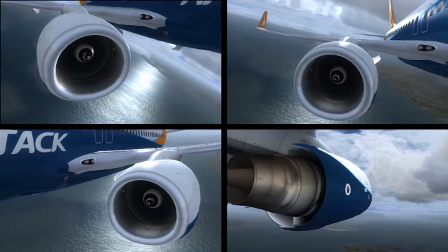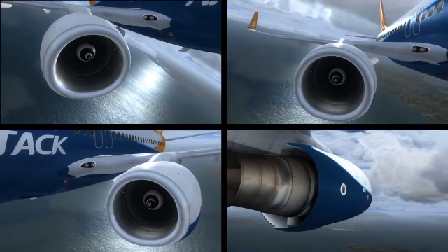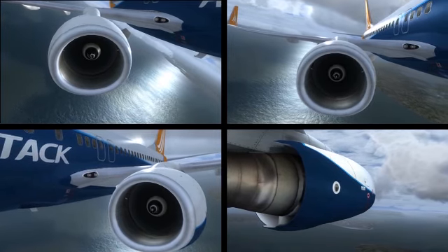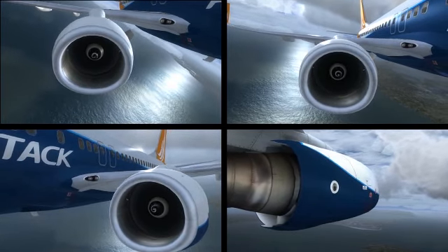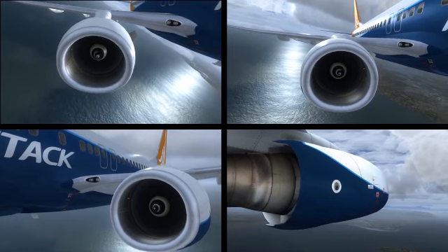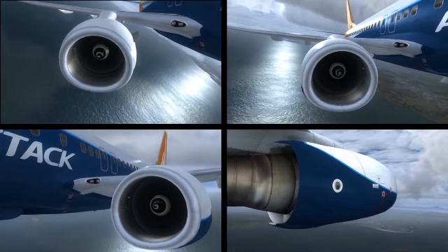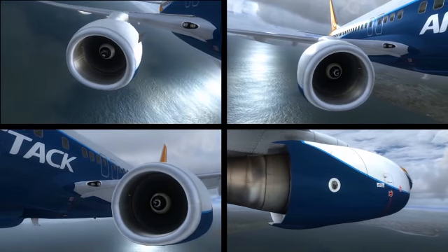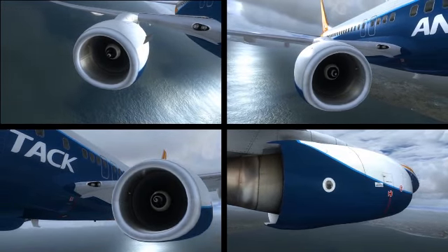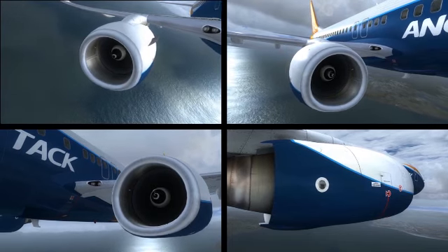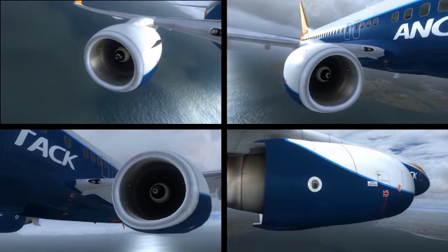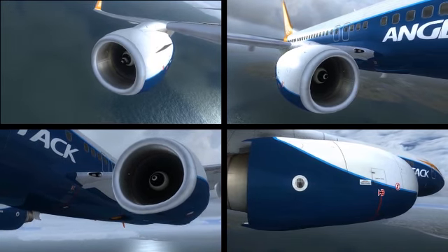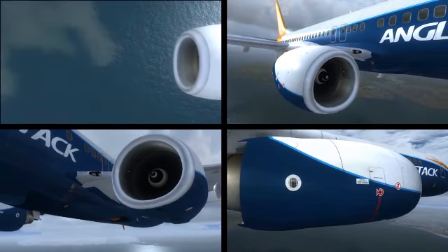Because the engine-driven pumps are mounted on the accessory gearbox, there is no need to select the engine pump switches off on shutdown. It is actually advised to leave the engine pump switches on during shutdown to prolong the life of the solenoid valve. The electric hydraulic pump switches simply provide and remove power to the electric pumps. We don't want to turn this into a lesson on the electrical system, but it's important to understand how each pump gets its electrical power and how that provides further redundancy for the hydraulic system.